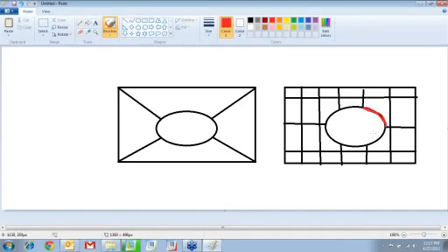This is the geometric boundary, and you can see the shape of it is not straight. Most of the softwares which use H-type FEA, including ProEngineer, the H-type FEA has a limitation of the element edges not being of higher order. For example, a straight line is y equals mx plus c. A curve would be like, say, a second order equation. A cubic curve would be a little more complex than that, right? Now, what will happen if you use a straight line to mesh this curved surface? You will have an error over here. To avoid that error, you will create smaller elements to match that boundary. You're making the error smaller, you're not eliminating it.